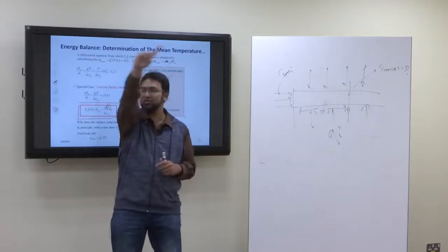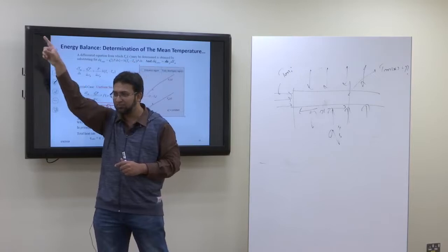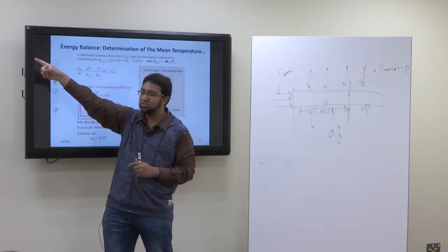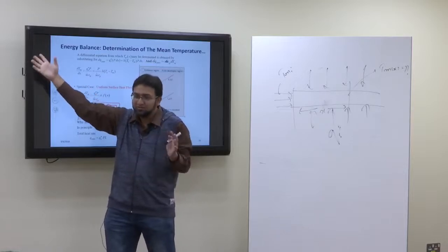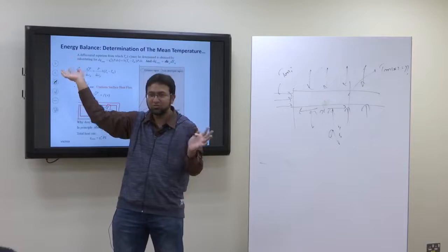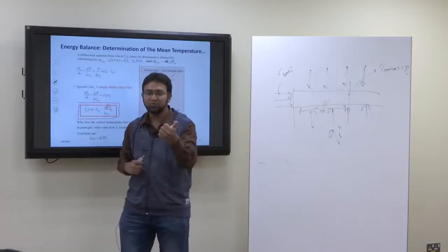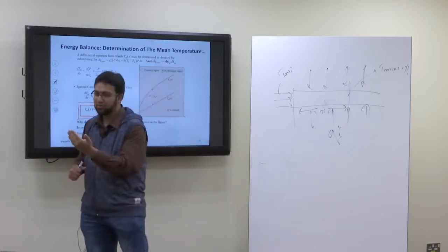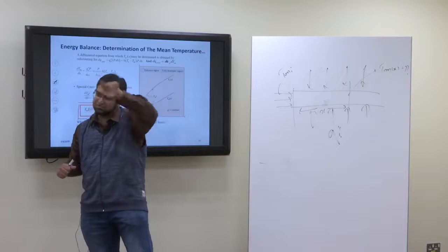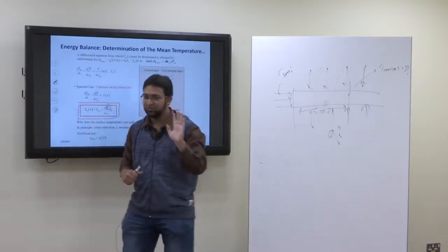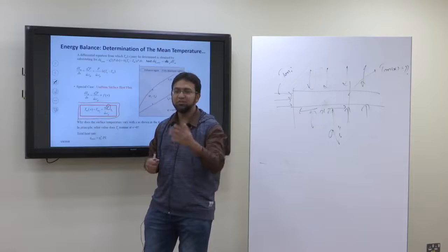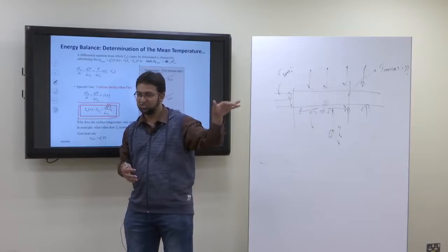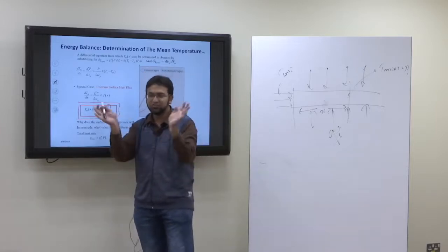The pipe is a closed circuit, so it's flowing continuously, right? So that means there it is the T mean inlet. It's not T infinity. It's not coming from outside and entering into the pipe. When we talk about T infinity, it means water entering from outside into the pipe. But if it is already in the pipe, it's T mean. We consider T infinity as outside the pipe. So there is no free stream now.